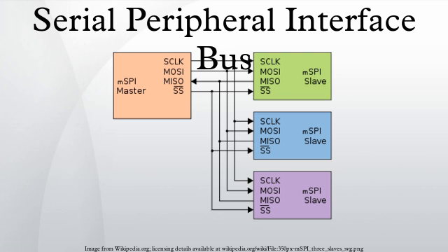If a waiting period is required, then the master must wait for at least that period of time before starting to issue clock cycles. During each SPI clock cycle, a full duplex data transmission occurs. The master sends a bit on the MOSI line. The slave reads it from that same line. The slave sends a bit on the MISO line. The master reads it from that same line. Not all transmissions require all four of these operations to be meaningful, but they do happen.